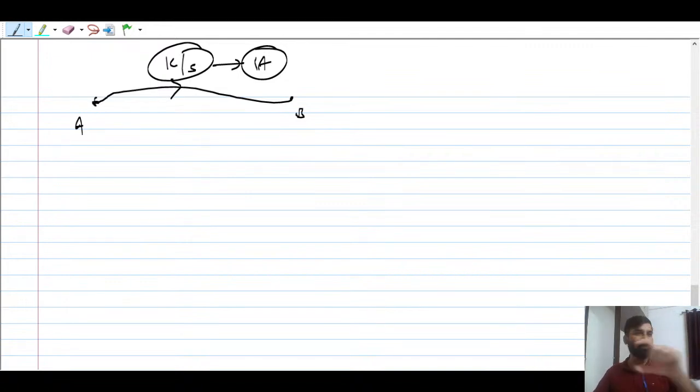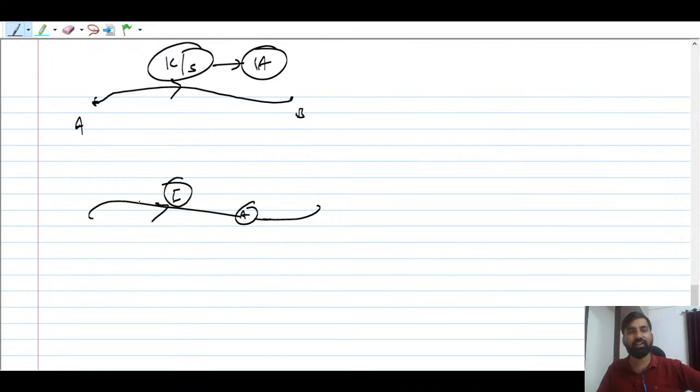We always put one ammeter, right? देखो, that is also very important. So suppose this is a wire, and how can we say that there is a current? So you just break somewhere, right? You can break here, okay, and you can connect a 1 ampere ammeter, right? Current ammeter. So it will tell you there is a current. And remember that ammeter is basically a device which measures the current. So make sure that this has series resistance which is 0, okay. The resistance should always be 0 in case of ammeter, right? So that it should not disturb anything.